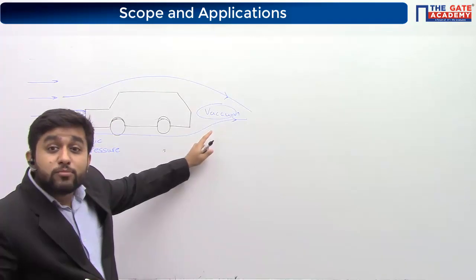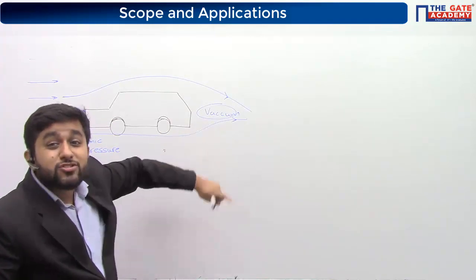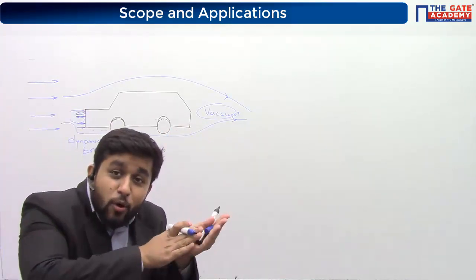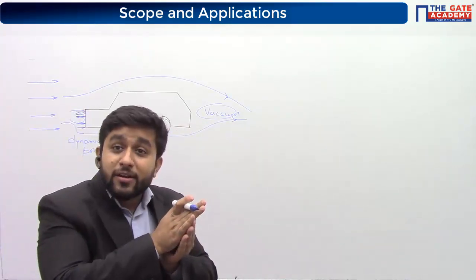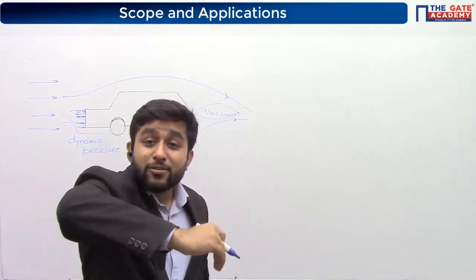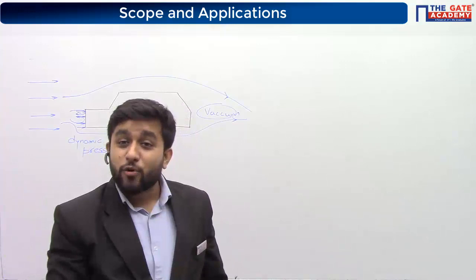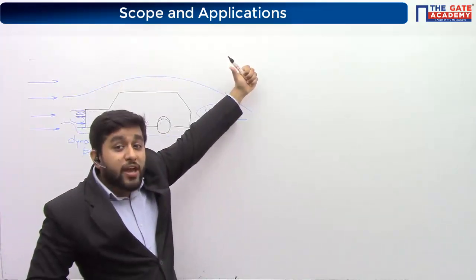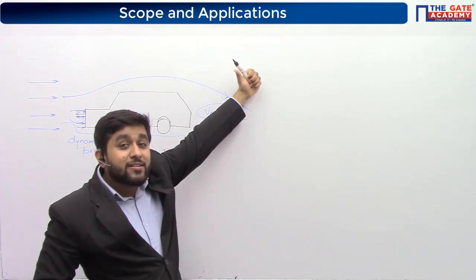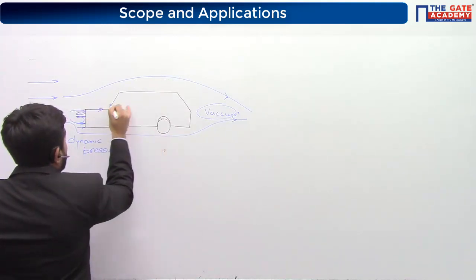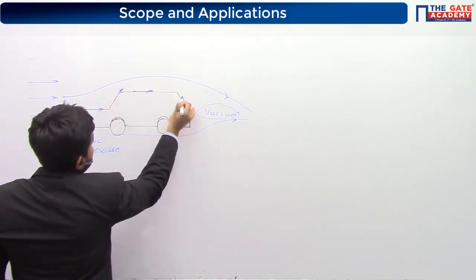So some partial vacuum is created over there. So there is an extra push. And not only this, when two solid bodies move with respect to one another, there is friction force. Similarly, when air moves with respect to a solid surface, there is friction force. Now check, air is moving in this direction. On the air, the friction force will act in the backward direction like this. So on the solid surface, the friction force will act in this direction.